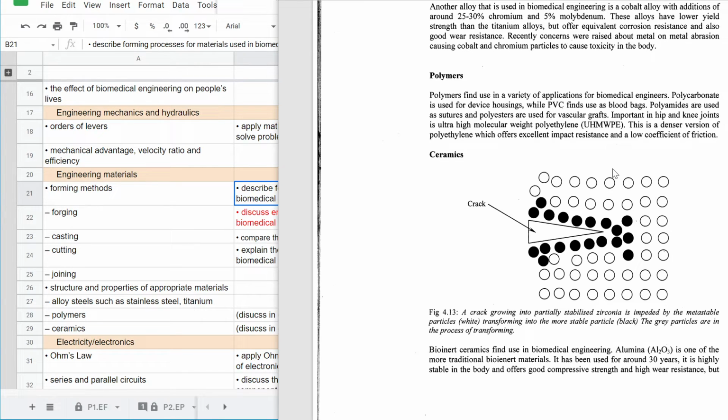Well, it's a bad analogy because it's not really in any way the same concept, but I think it's the closest thing that you might deal with in your day-to-day life, which is that you can have partially stabilized zirconia, right? So you can have zirconia in an unstable phase, metastable, where you can squash it into a formation that is taking up less room than it really wants to for the temperature and other pressure conditions. And so what happens is when a crack forms, it can release that extra energy and it can fill up the crack.